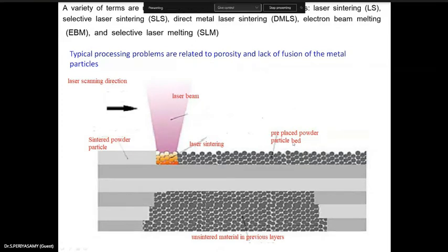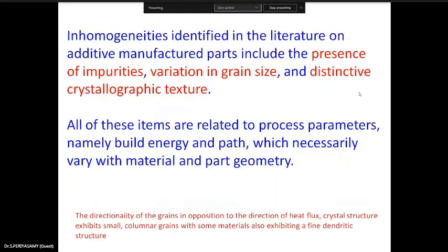For the density, you have hot isostatic pressing. In that, you have small holes. Even in the hot state, when you are compressing, you still have small holes. So this may be controlled through the process parameters.